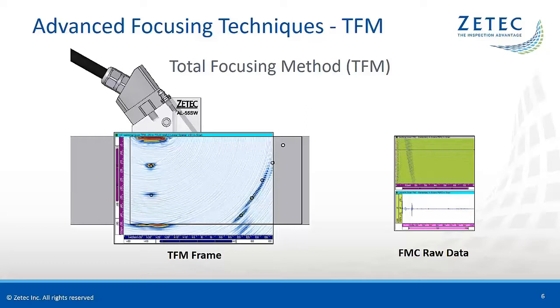I will show later that the focusing capability of the technique still depends on the acoustic wavelength and the total aperture of the array. Therefore, some conditions must be met to effectively obtain ideal focusing.